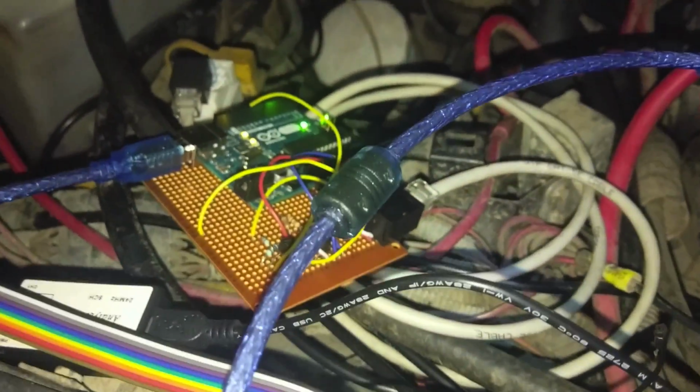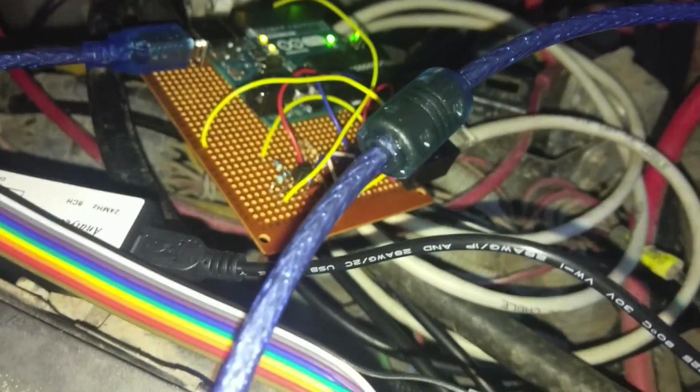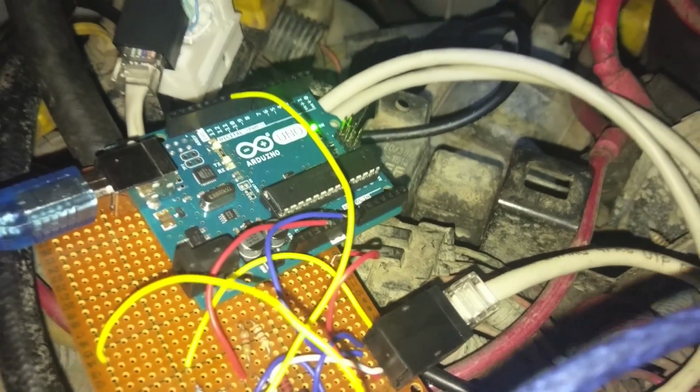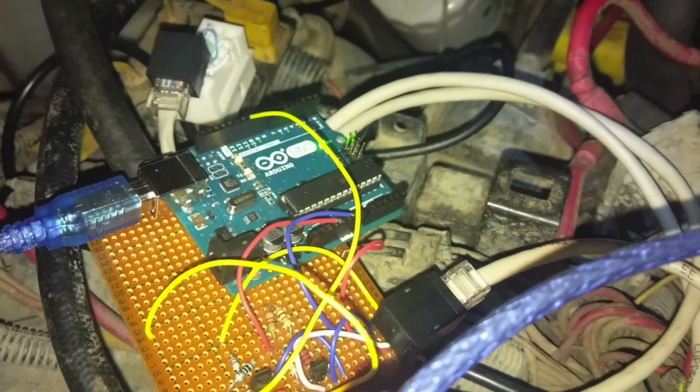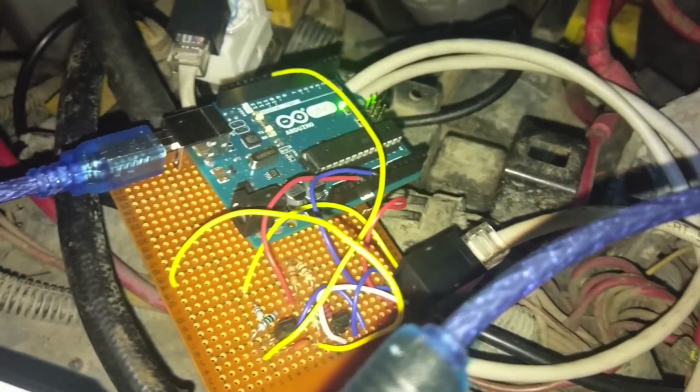Okay, so we get some good news. I tried messing around and figuring stuff out, and I didn't really see anything because it seemed like we got a good high and a good low, and the logic analyzer picked it up and all that. So I was wondering if maybe the RX, the actual hardware UART on this thing, was just giving me issues. So I said, screw it. We're not going to be using that anyway. I'm going to be using software serial.